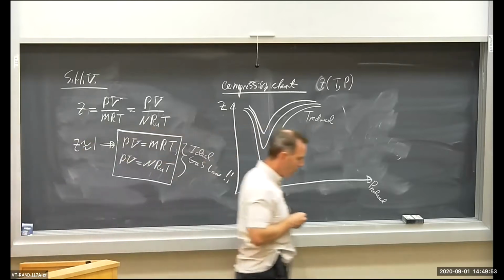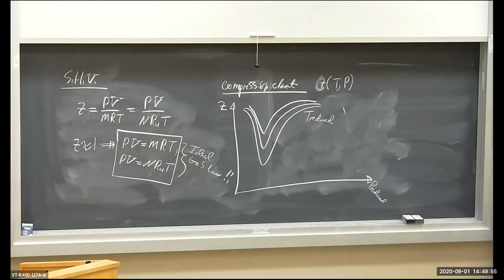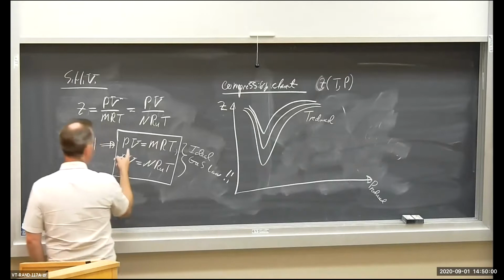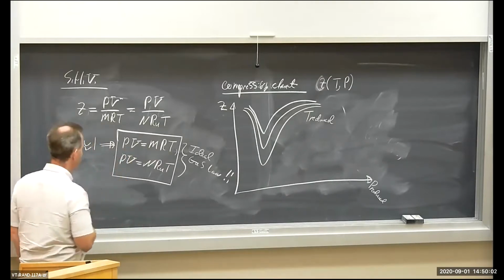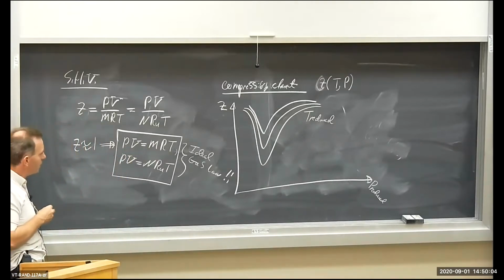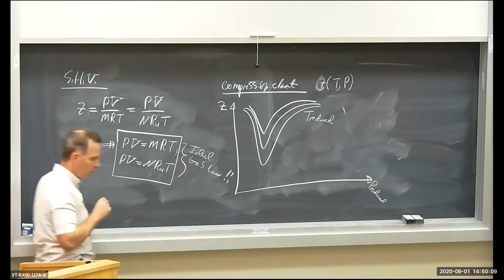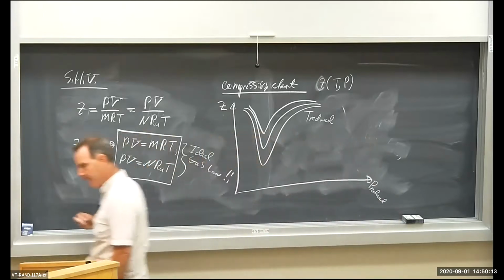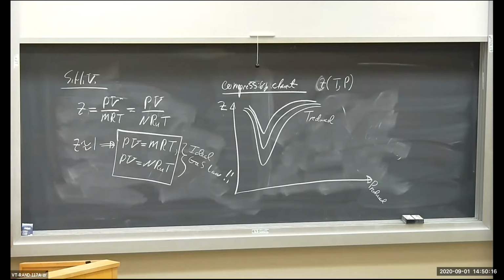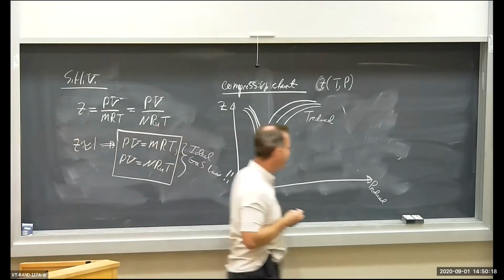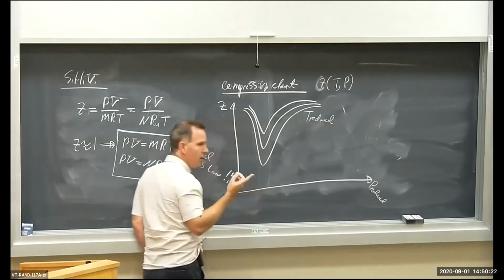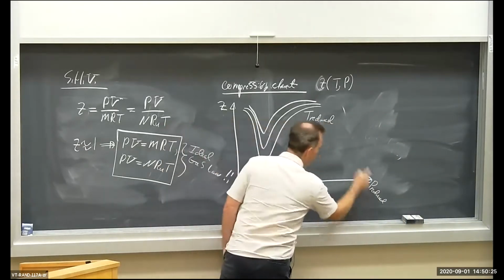So when Z is approximately equal to 1, when we have a good temperature and pressure range at which Z is 1, or nearly so, then the relationship between pressure, volume, temperature, and mass becomes very simple. And we can calculate properties for superheated vapor with relative ease if Z is approximately equal to 1. Okay? Now let's figure out where Z is approximately equal to 1, under what conditions. First of all, let's define what we mean by reduced pressure and temperature.